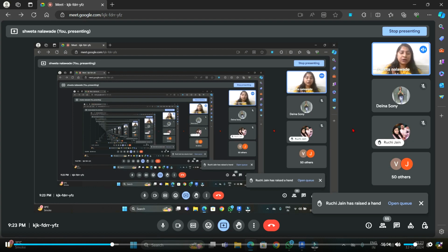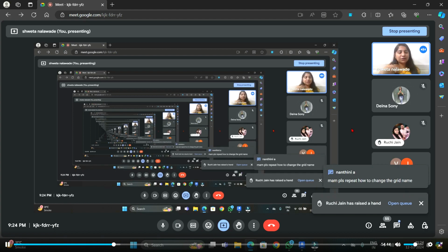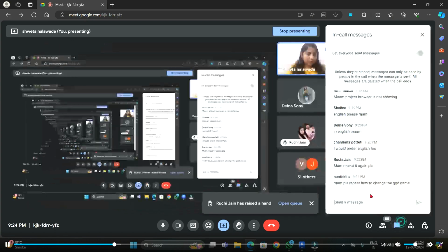What are grids used for? As I said, they'll be used as your center lines to locate your columns. So according to your columns, it would get placed, not randomly. Clear? We'll come to columns. 5000 is just for your reference right now.